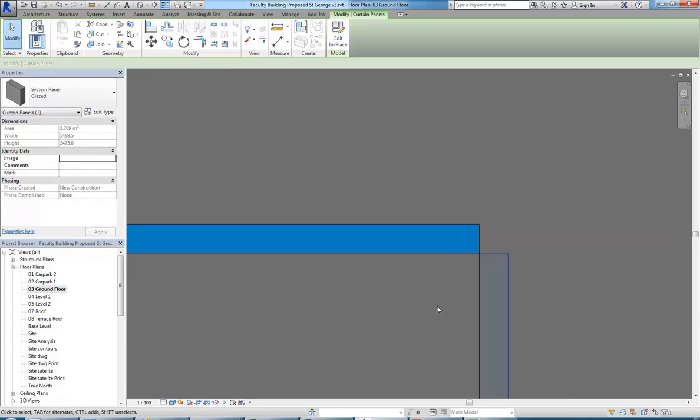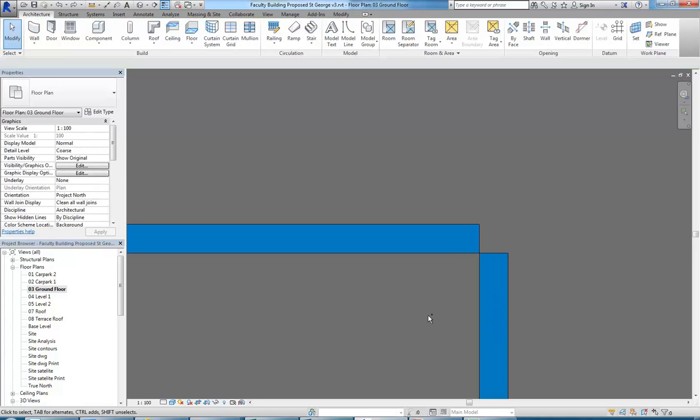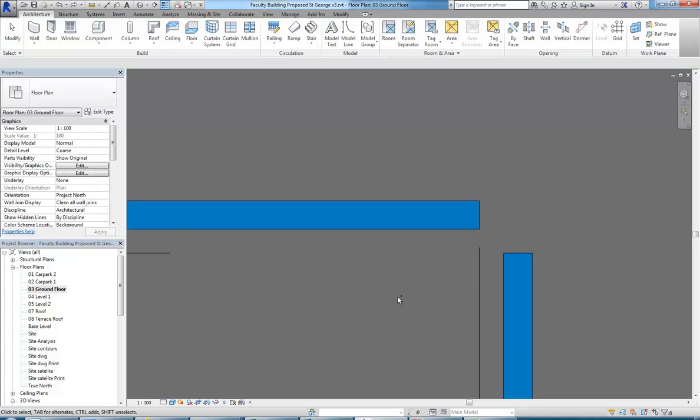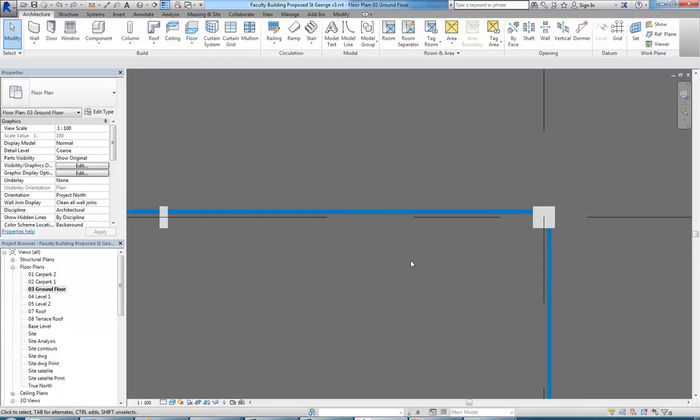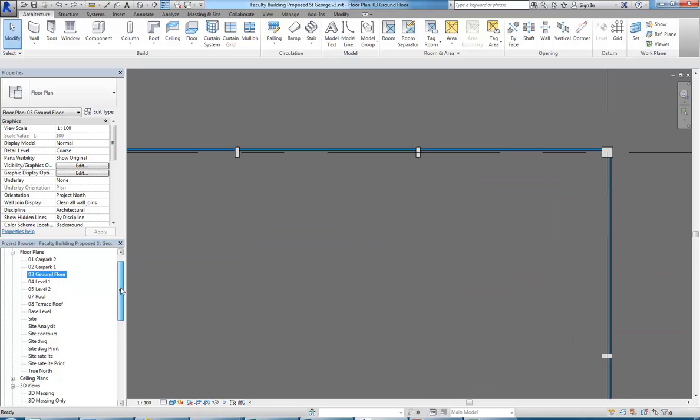That's right, exactly, because in real life they would be flat panels of glass, and then you need a silicon joint in there to fill that corner in. You can get big sheets of glass these days. You can go up to 6 metres, but even so, they're going to be squared off at the end. The frameless looks fairly popular these days, but I think it doesn't hurt to have mullions, and they can still be a nice part of your design.